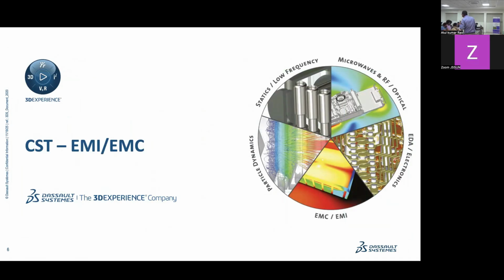Let's say we are designing an antenna for a vehicle, and it is over the surface, which is usually PET. If we want to run the simulation, the tetrahedral mesh will be very small, so the overall timing will be very high. So how do we simulate that surface?